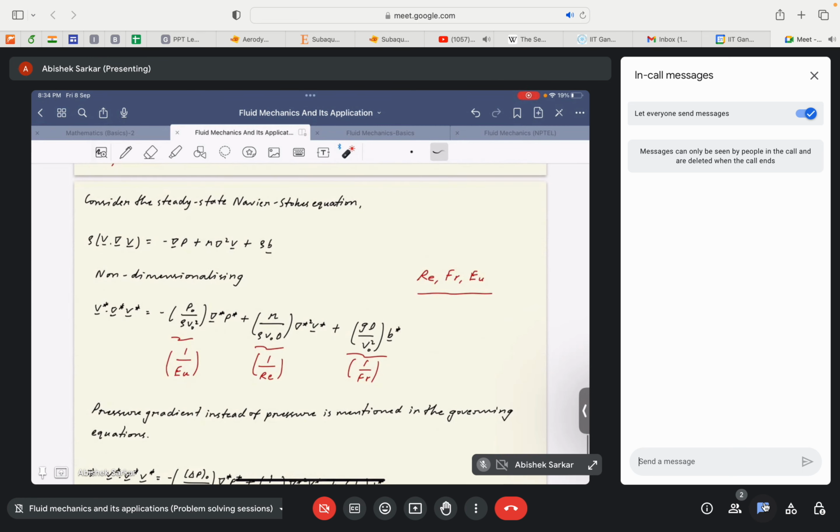It is because of that assumption only we were able to non-dimensionalize this vector from the equation by the same velocity component and the same length scale. Here, which is ideally not the case in different fluid flow problems. In the case of boundary layer, this is not at all valid because different governing equations along the different directions will have different length scales that will govern the flow field, right?